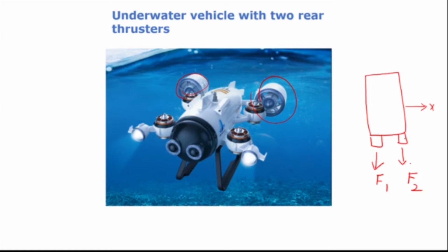That's an interesting question. That means although it cannot go sideways, can I go and park it here? That is almost like saying it is going sideways. So the answer is yes. It cannot go sideways, but I can have maneuvers, not with one maneuver, but a number of paths by which the robot can actually go and park sideways. So it appears that it can go and park here. So this configuration is possible, although not in one shot. In our path planning, we'll talk about these kinds of problems, that is, what are the different paths it has to follow such that it can go park sideways.